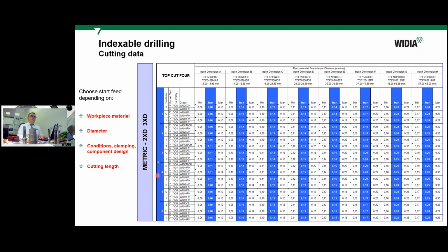And you can see that this chart is related to short types of drills, if I can put it so: short, 2 diameters and 3 diameters. I don't mean 1 diameter. For 4 diameters, 5 diameters length of the drill, there are similar charts here. So these charts include almost all conditions we can face: conditions, diameters, and also length of the drill, depth of the hole.